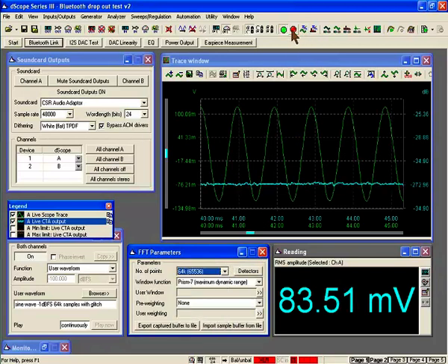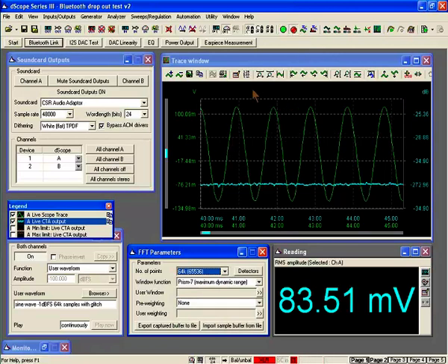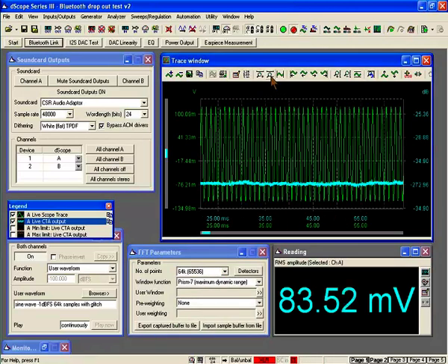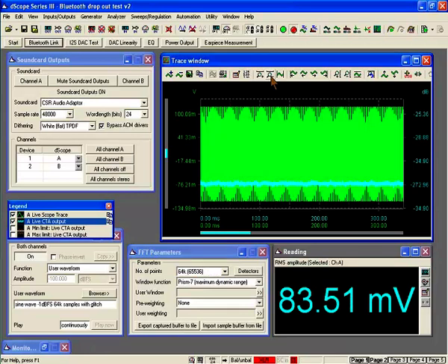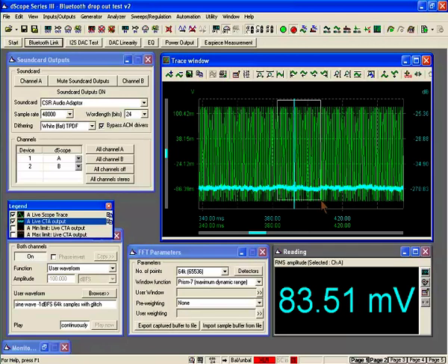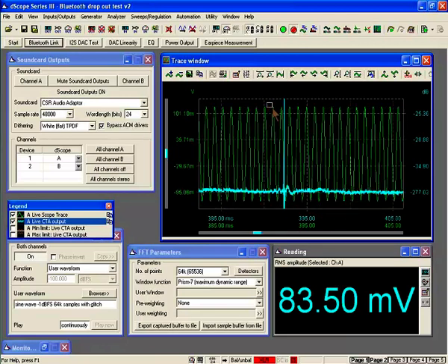And if I just measure a relatively large FFT capture here, let's take a look, if we zoom out, at what we see. Now the sine wave looks fine, the noise and distortion trace looks fine. But what's that? Let's zoom in here and take a look. We can see that there is a significant glitch in the residual noise and distortion waveform here, and if I